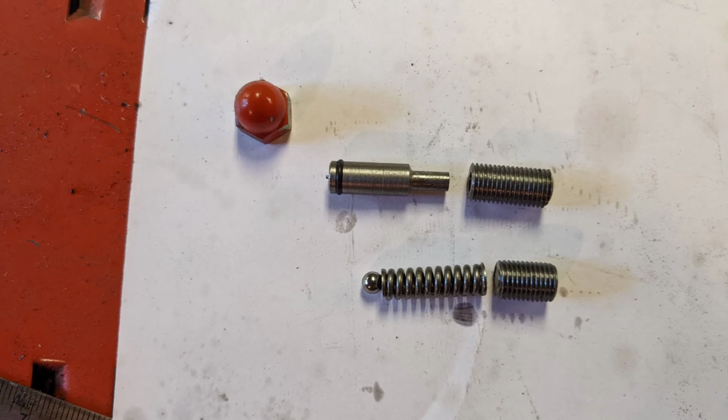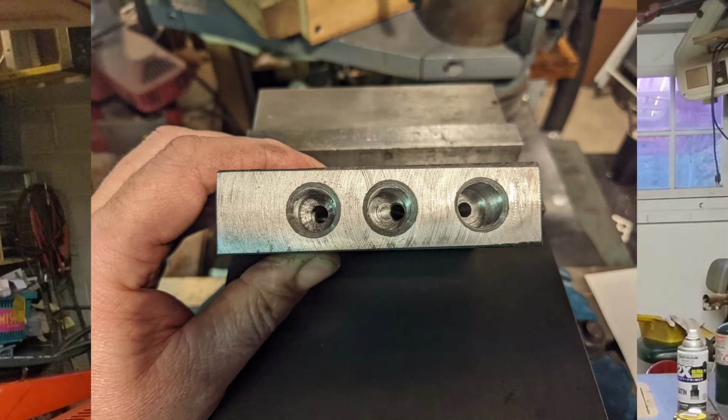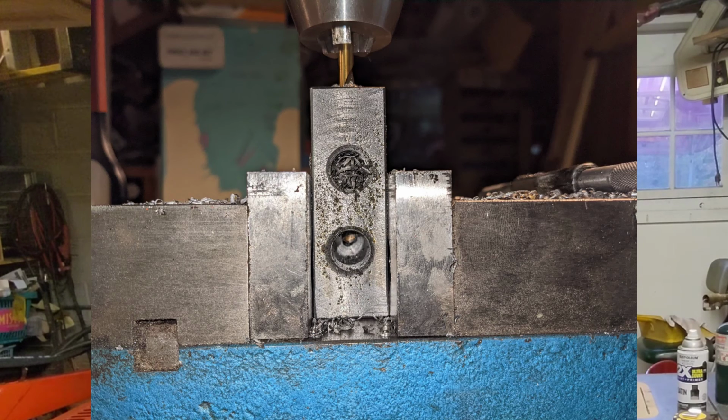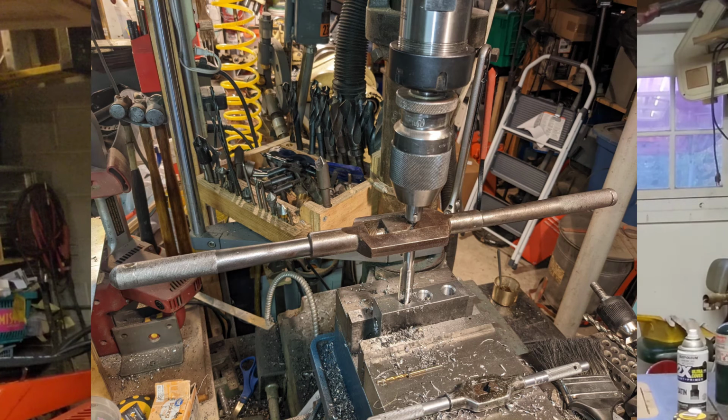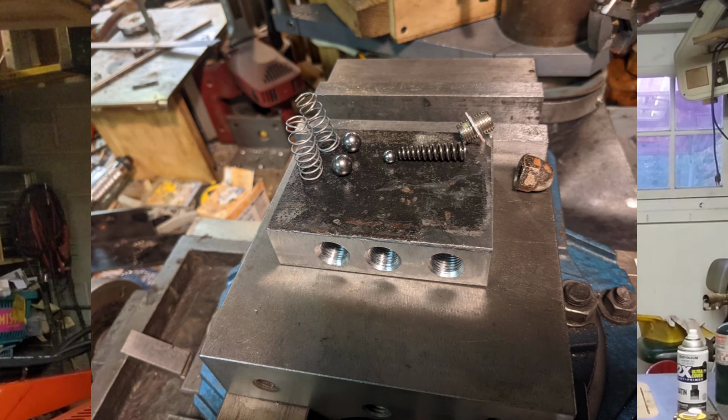I removed the pressure relief ball and spring from my existing treble control valve and replaced them with a slug insert that would completely block that port, so it no longer functions as pressure relief at all. In the process, I measured the size and depth of the spring chamber so that I could machine an identical port into my new component. I machined that port and the other parts of my newly invented hydraulic device. I didn't have the right springs for the inlet check valves, so I wound a pair of springs on the lathe using some spring wire.